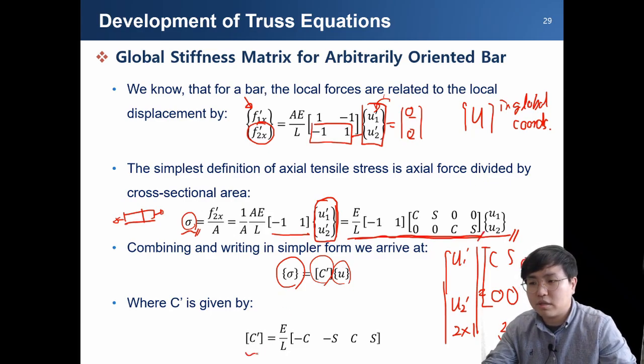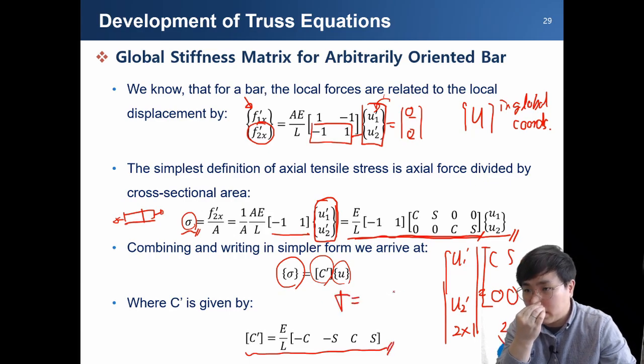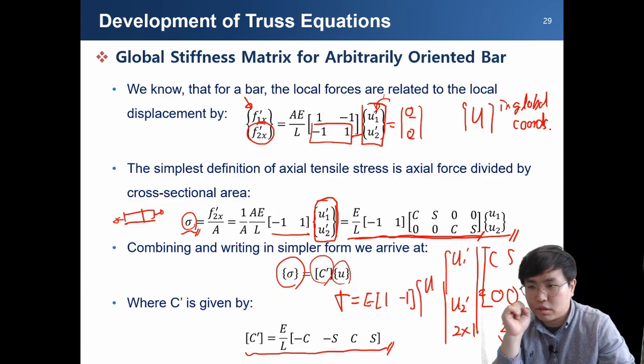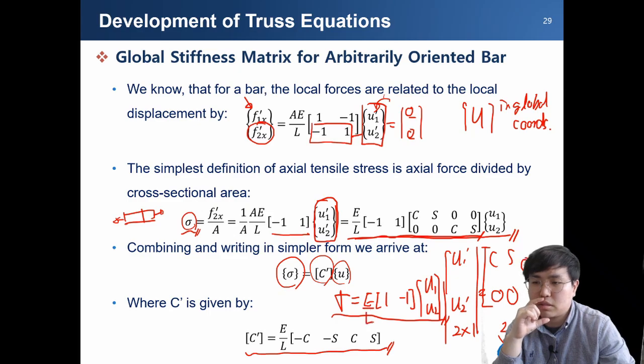So this is a stiffness matrix. In the previous slide, we already said the Young's modulus and maybe 1 and minus 1 is this expression of the stress in the local coordinate system. I also made a mistake in this slide. So this is the stress expression. However, if this one-dimensional truss element is rotated, we should use this kind of Young's modulus matrix.